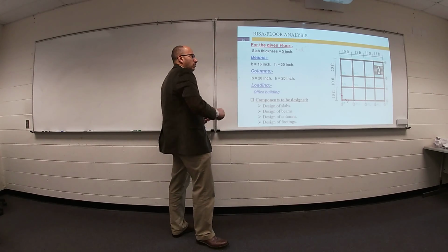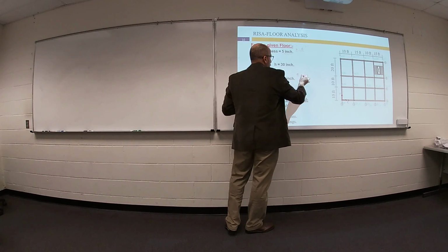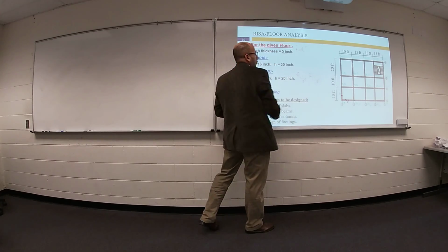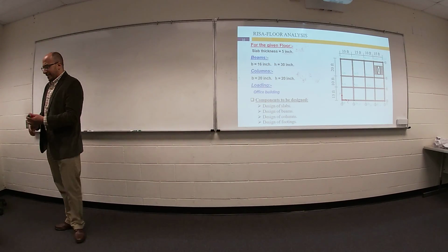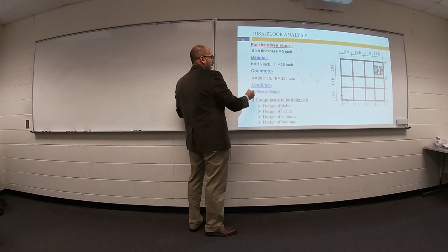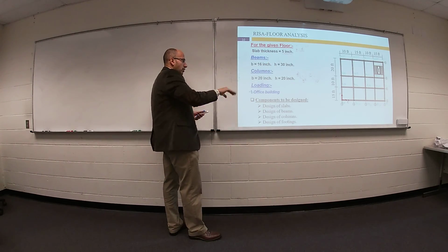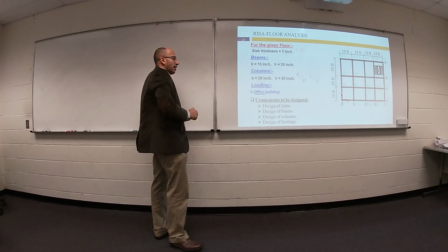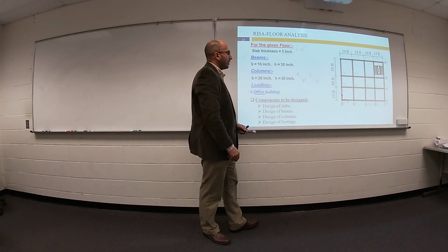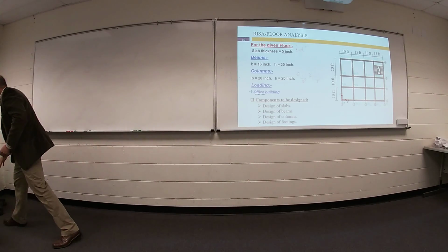Your column, you can assume what you want, but the minimum cross section of your column is 8 inch times 8 inch, or maybe 10 inch times 10 inch. This one is okay, this one is okay also. Your building is an office building. From a table I can figure out the live load, or in your software, just choose office building, that's all. We need to design slabs, beams, columns, and footing. Let's start to redefine this building on RISA Floor.